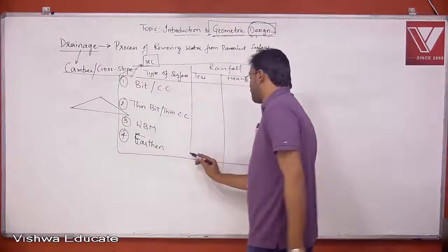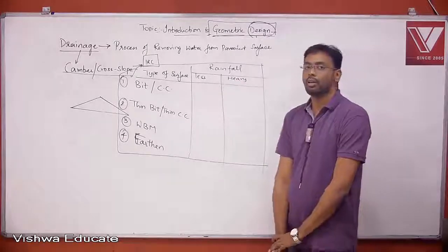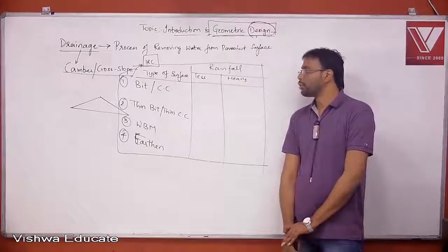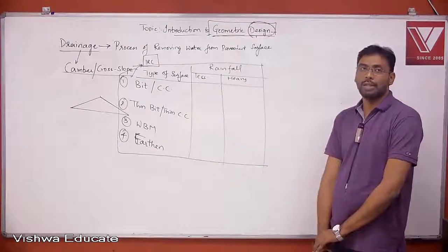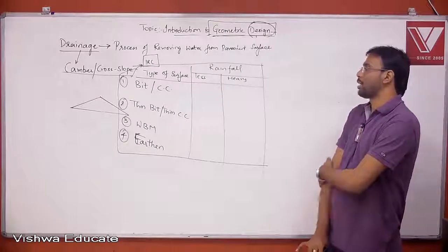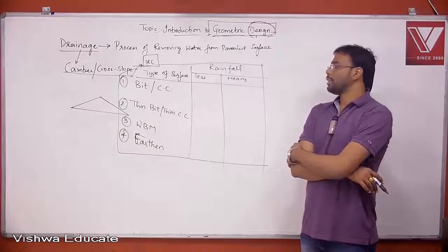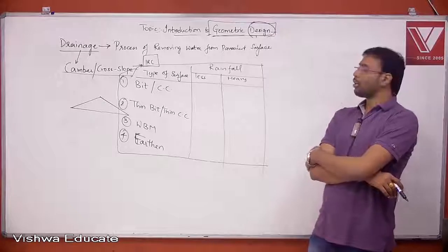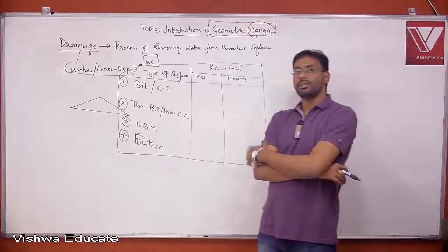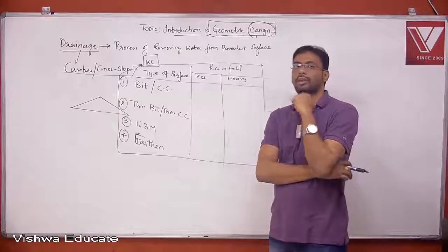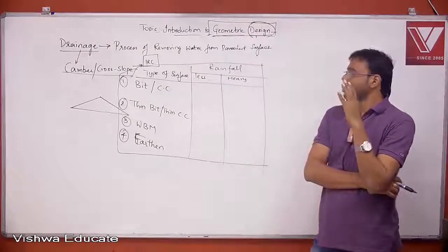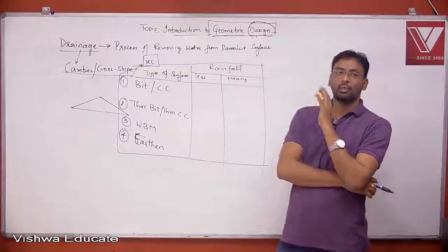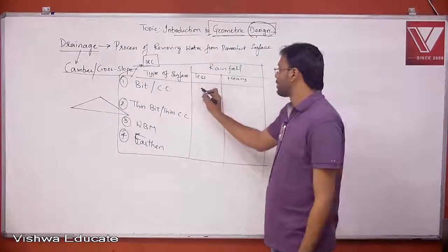for solving problems related to the camber or related to this topic, you need to know these values. So you need to remember this table, these values mentioned as per IRC. But of course, it is very easy to remember. And as I said, camber is nothing but a cross slope. Cross slope can be represented in three formats as I discussed already in the last session. So here I am using the percentage format first. It is very easy to remember. It is 1.7%.